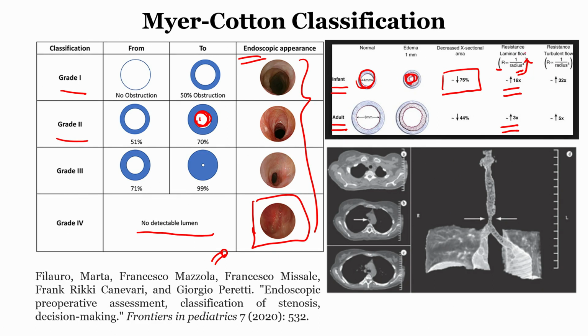And when the flow is laminar, it is still okay, but when it becomes turbulent, the power is in turn rising 5 times. So, you see how the channel geometry plays an important role in the fluid flow through these airway structures or the circulation system. This here we call, in medical terminology, stenosis, that is reduction in the cross section area when compared to its healthy diameter.